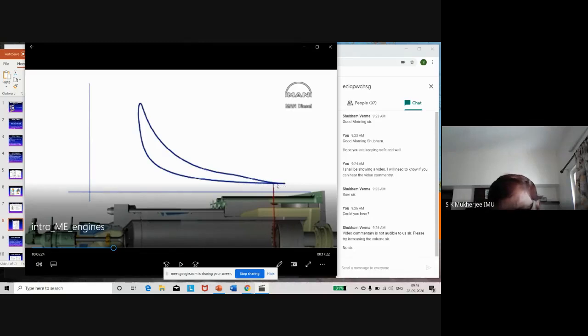And then when it starts moving up, you have the pressure already in the cylinder and the compression starting. So this is the diagram for the two-stroke engine, and the area enclosed by this diagram is indicative of the work done. If you see at this point, the pressure gradient is much faster.